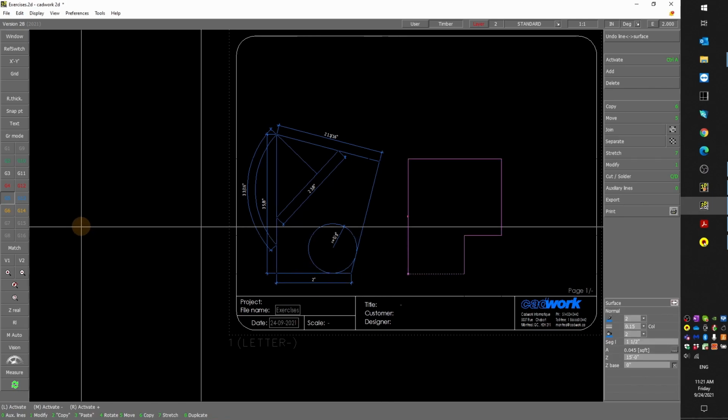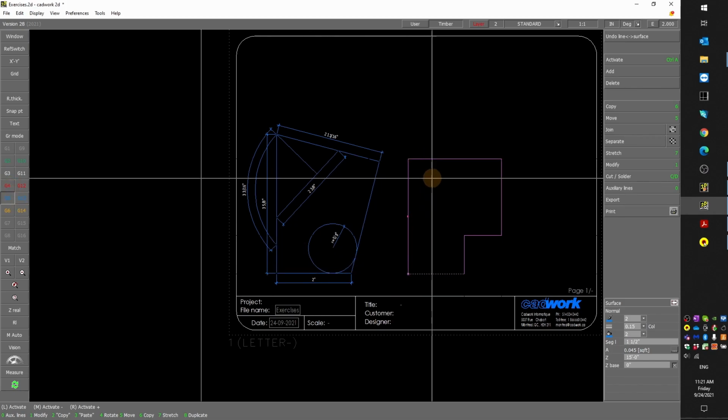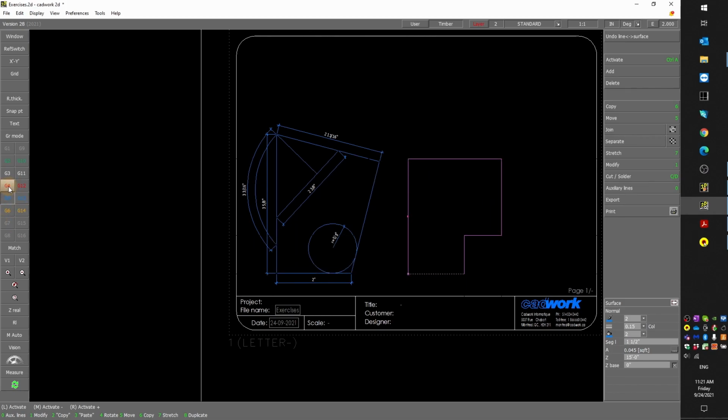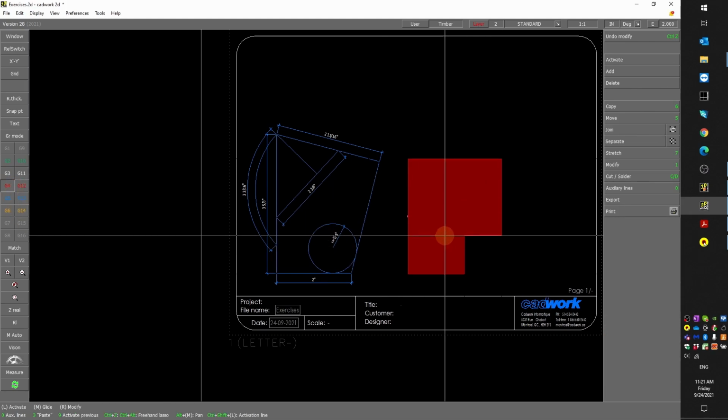If you'd like to set it to G4, you can select items and then middle click. You see that middle clicking modified the selected items with the current graphics settings. So if I middle click on G4, now I just changed the settings to G4.